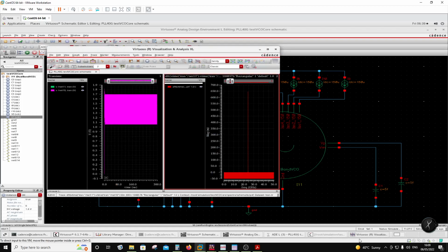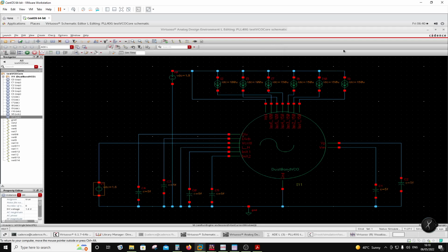I have nothing to speak on other than this, which is 24.37 gigahertz. Later, I am also going to switch these. Basically, the currents I'm putting right now are large currents. For the VCO which is off, I'm going to switch off 3 of these current sources, so the drain of this current is minimized, and you can probably put it in sleep mode, because you can have an individual switch for the 2 VCOs. So basically, you can put the PLL into a standby mode. Switch off the entire thing here, and similarly you can switch off the mesh, the divider, and everything, so that the static losses can be minimized during standby, right? So that can be done.